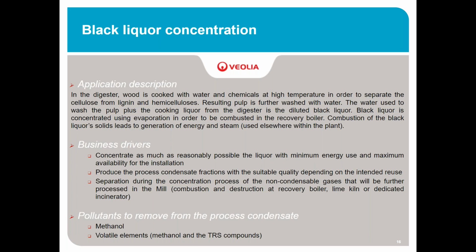So you get condensates with the water, which have to be tailored to mill usage, and then you concentrate the liquor typically up to 70 to 85% solids, where it can be burnt in the recovery boiler. The organics are burnt off to generate power to run the mill and generate electricity, and the chemicals then go to the lime kiln and they're recovered back in the process.